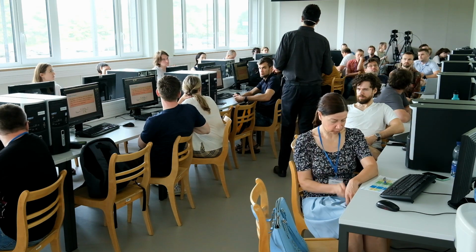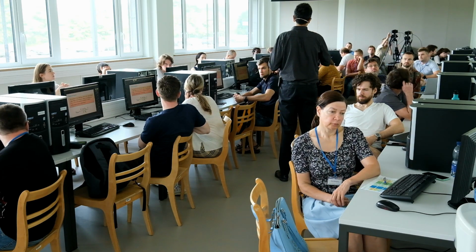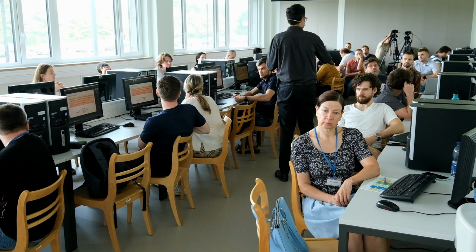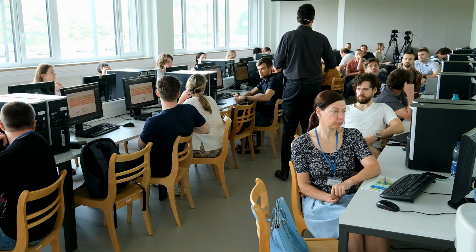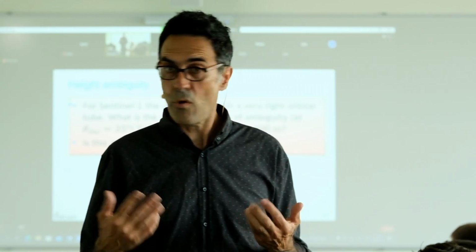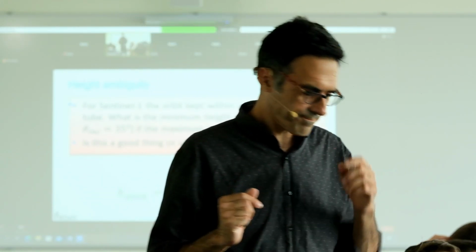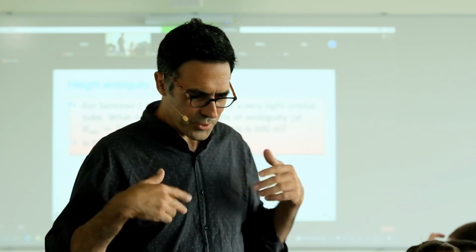So the one thing is easy, that is time, right? These reflections will come back at different time intervals. So we know that all the reflections which come from a certain time interval come from a little band at the same range, right? But then I still don't know where in that band it is. So the second thing is in the azimuth direction, and we do that by focusing the image. So basically, I always explain it like this. Suppose that I am the satellite, and this is my satellite beam here, and you are the target, right?